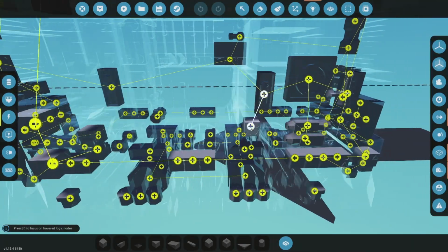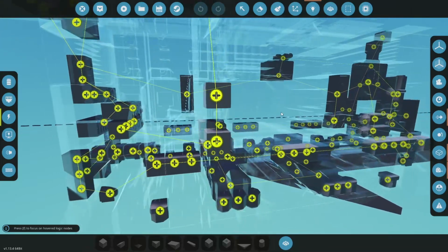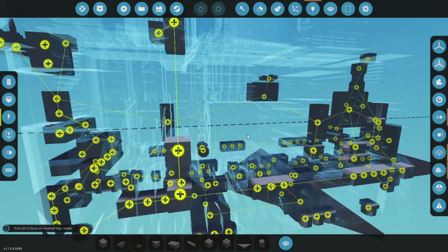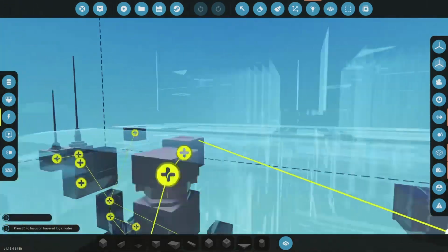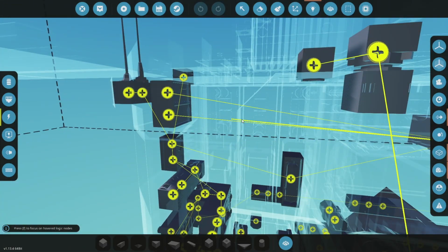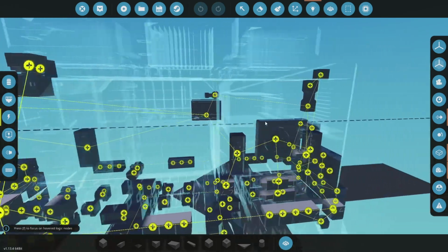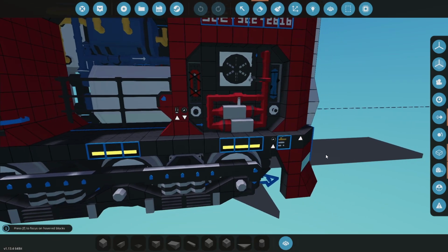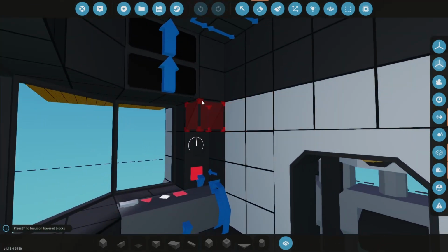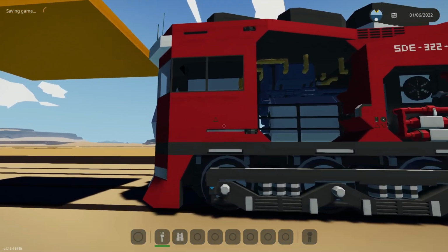Look how I've done the electricity. I used to be real big on doing this because it meant you could kind of clearly see what was connected. But I am no longer a fan of this. I would rather just run it all off the battery. In this situation, there is some reason because there's a relay here and that connects onto these back drawers to make sure they don't drain the electricity, but kind of annoying. When you want to add new stuff into the system, it's annoying to have to go through and figure out what's going to be draining electricity.